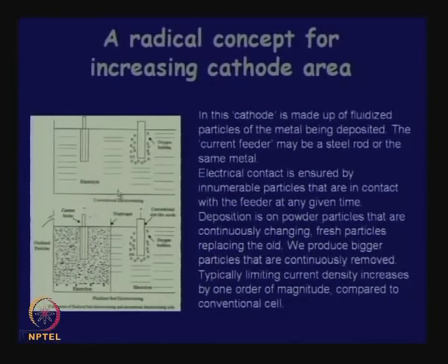So, suppose metal M in this solution is to be deposited. We take powder of metal M, have them dispersed in a thick suspension, and that is fluidized. Means, if you leave the powders as it is, perhaps they will all come here and make a bed, but then the electrolyte has to be pumped through the bottom with a certain speed, so that they are thrown up and they are fluidized, they cover the entire area. Now, you might say, what is happening to the electrolyte you are constantly throwing up? It will come out this way. How? I will tell you.